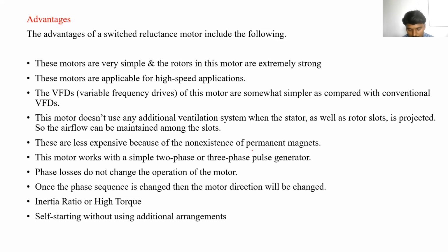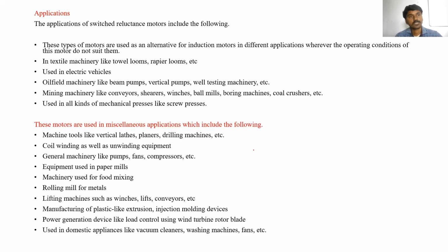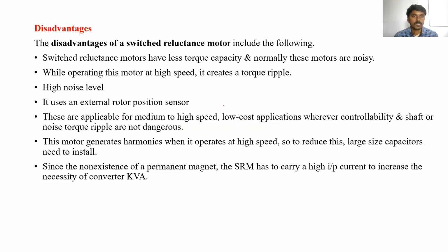This switched reluctance motor is a self-starting motor, so there is no need to use any additional arrangements. In the case of a single phase induction motor, we have to use a capacitor because a single phase induction motor is not self-starting. Clear? Here there is no need. The switched reluctance motor is self-starting, and this is also an advantage.